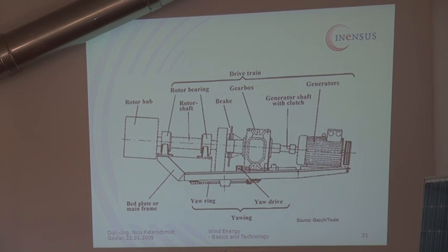And then here you can see some very important safety devices. As a wind turbine manufacturer, you have to take care of your wind turbine being N-1 safe, like fail-safe. If one failure occurs, this turbine still has to be safe. And therefore, you usually need two independent braking systems. That is required by the major standards, the IEC 61400